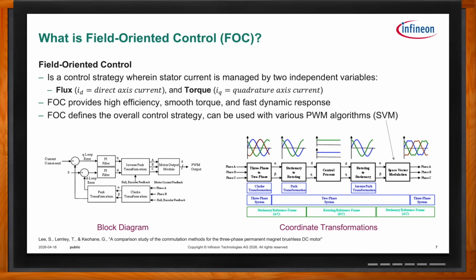So I already have axial flux in the machine, but by energizing the windings in a particular way, I'm able to either increase that flux or counteract it and decrease it. And when I do that, it changes both the torque constant, Ke, and the back EMF constant of the motor. So I can kind of change the characteristic of the motor, and independently, I can also control IQ, the quadrature axis current, which directly drives torque.